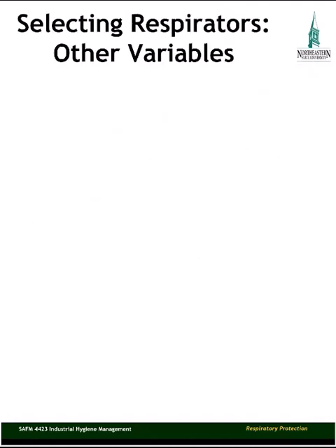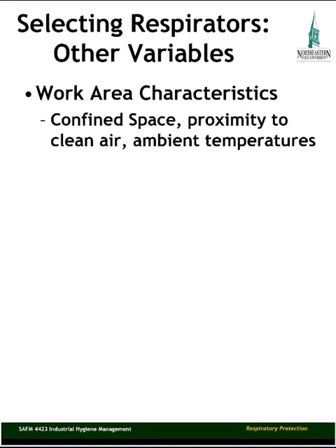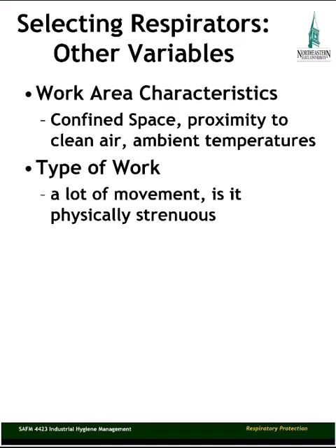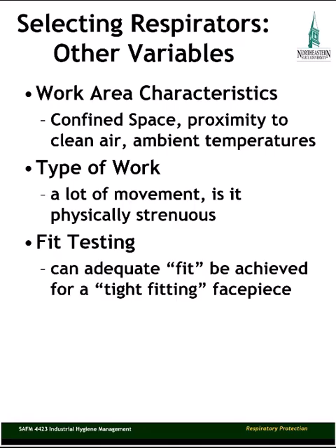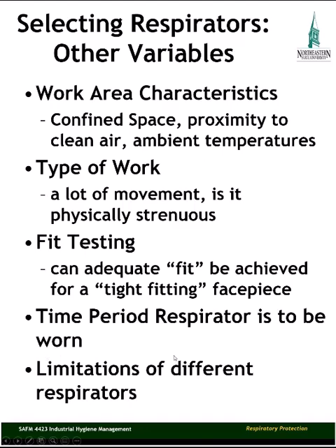So some other variables we need to consider when selecting respirators. Work area characteristics. Is it a confined space? How hot or cold is it in the space? How close are we to clean air in this area? The type of work we're doing. Is it physically strenuous? Pay attention to how the area where you're working affects the fit of the respirator. Can an adequate fit be achieved for a tight-fitting respirator? Another variable to look at, how long will the workers be wearing the respirators? Also, you always want to consider the limitations of different respirators.